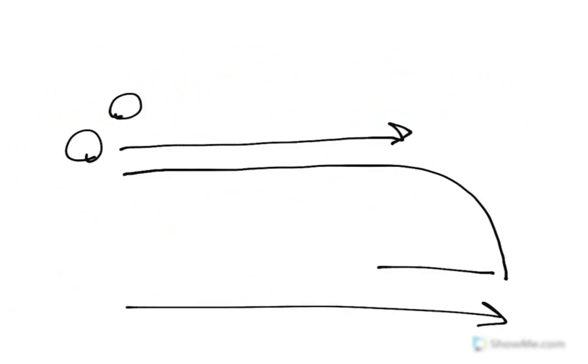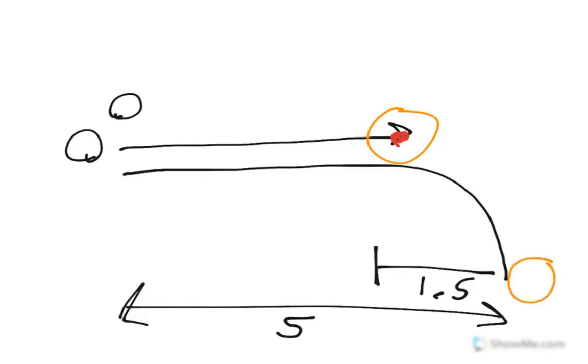So let's take a look at that first portion. We're going to move straight and then move down. This is our 0 point here. So as we move straight over across, we're going to move a distance of 5 is the total distance, but what we're looking for is to subtract the 1.5, where we're going to stop for the center point of our circle. After that, it's going to traverse a larger arc than we're used to, and then finally move onward in a vertical direction.